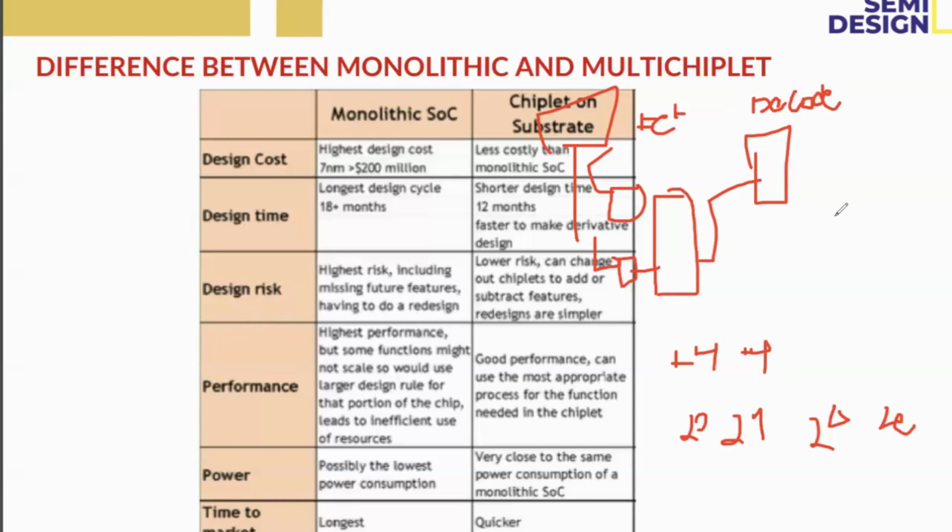Decode is nothing but here there will be some ALU. Suppose you are sending the instruction as an arithmetic one, then it will decode that instruction as an add to the ALU block diagram. If you are sending some logical operation like XOR or AND, that logical data will be converted using the ALU. So that happens in the decode. Once decode is completed, that instruction will be sent to the execute stage.